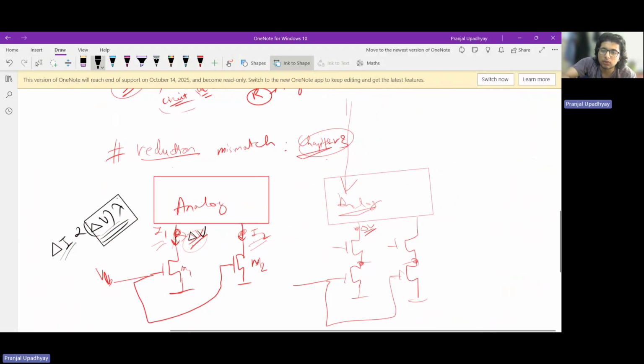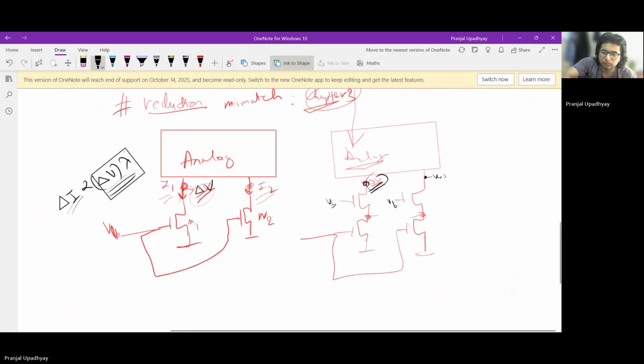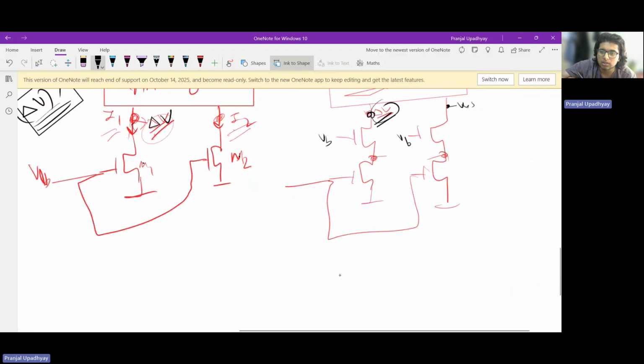And what will happen for a cascode, when we are applying cascoding, is that I am biasing these two guys, so this del V voltage, let us say that here the reference voltage is VDS and here it is VDS plus del V. If you apply small signal analysis, which means you are assuming the transistors are in saturation, the effective resistance this guy will see from the output is, let us just write the intuitive expression, gm ro squared, right?